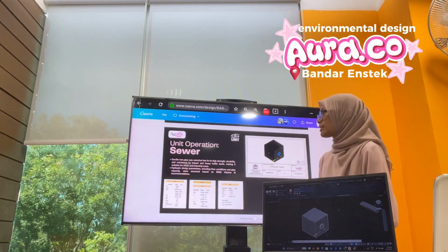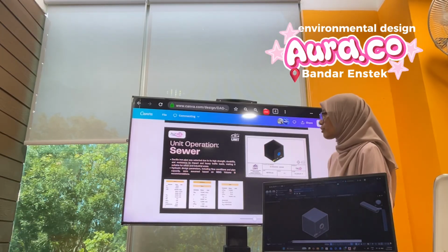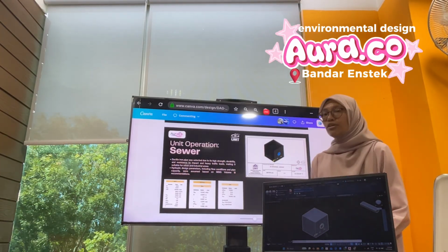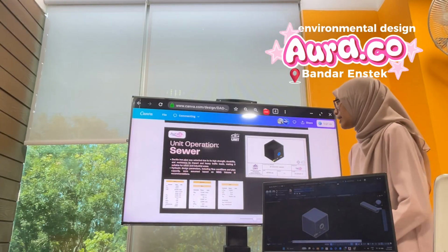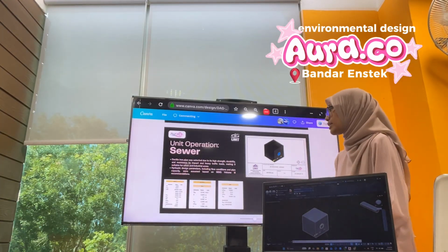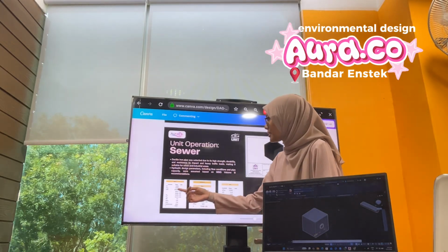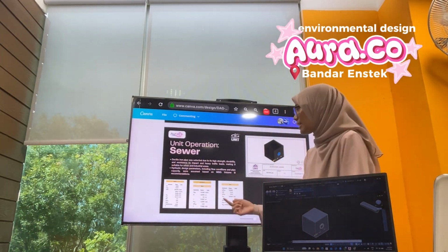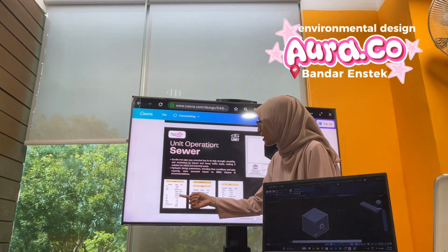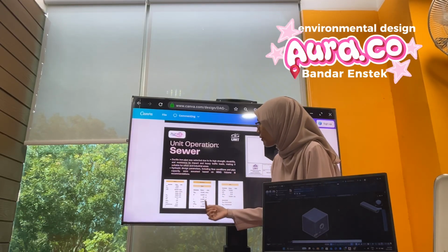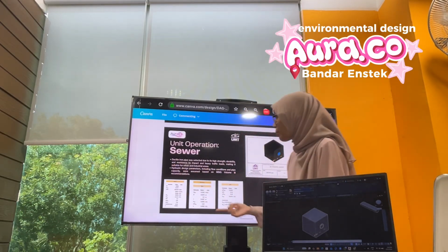The hydraulic design parameters including flow condition and pipe capacity were assumed based on Malaysian Industrial Guideline MSIG Volume 3 recommendation. Our PE is 13,300 and we calculate the FP, DWF, Qmin and Qmax.